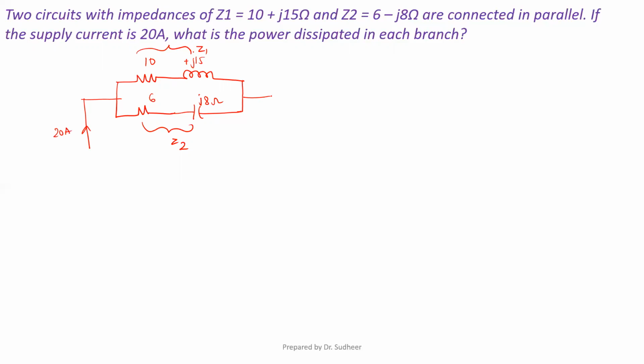How to solve this circuit? So you have to just analyze or go back to your network theory basics. When there is a total current passing through resistances R1 and R2, I1 is equal to, what is the formula? I into the opposite resistance by the total resistance, the sum of the two resistances.